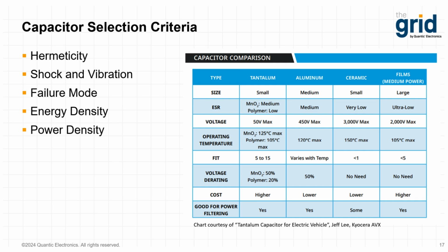Now, moving along to the failure mode, it's always a good idea to plan for the unknown. So, despite our best efforts as designers, failure happens. Obviously, capacitors can fail, but the way the capacitor fails should be something to keep an eye on. Solid tantalum capacitors are very, very popular and widely used. However, when they fail, they can fail open and catastrophically. And when I say catastrophically, they have the potential to actually catch fire.